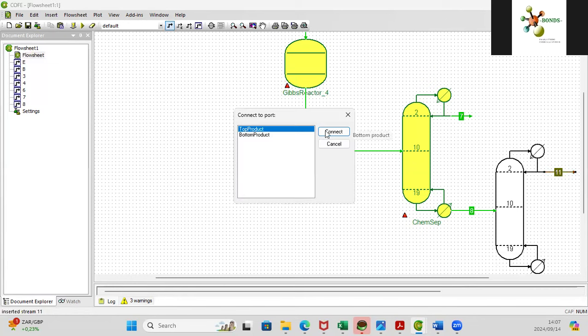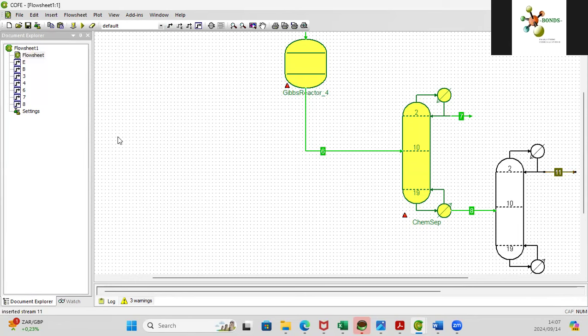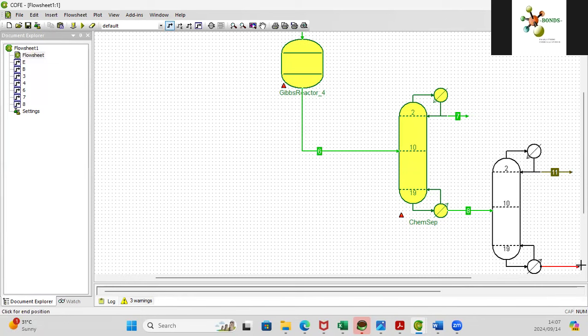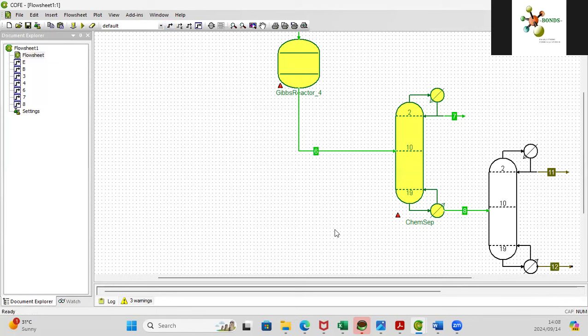For now, I just want us to look at the process flow sheet, the PFD, process flow diagram, because your process flow diagram is basically a schematic process description. And that's what we're doing. The first part of your conceptual design is coming up with your process description, which will have your PFD, your stream tables, and your written process description.